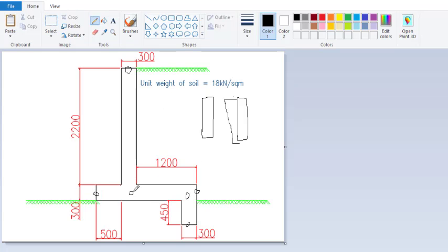So I have this node, I have this node, and I have this node. So let me deal with this other node. This particular node should be 2000 mm minus 150 mm. Remember that the width of this toe beam is also 300. If I subtract half of this width, which is 150, from the whole length, which is 2000, that will be 2000 minus 150, and that will give me 1850. Okay, so I will have this node like that.